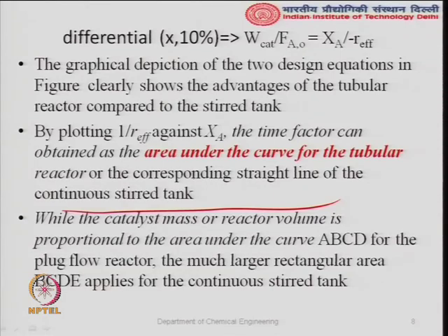So, either you look at some jacketed or adiabatic reactors and select those accordingly, or you use a slurry bubble column reactor or fluidized bed reactor, which are nowadays more common, especially when you have exothermic reactions, when the heat generation is a problem and dissipation of that heat may cause hot spot formation. So, then these become very important.